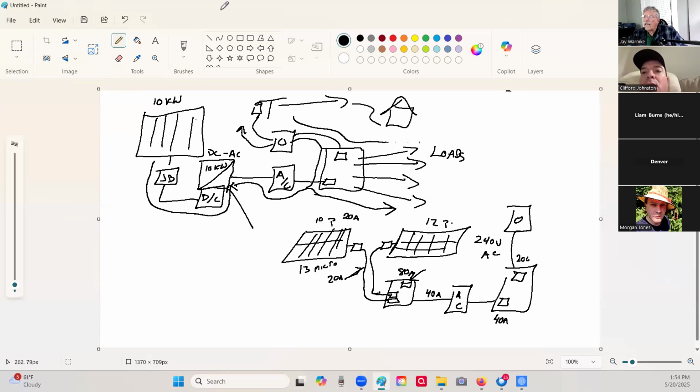Okay. Now, on each one of those microinverters, there's an LED light on the side of it. And if you go and look underneath, if that's green, that means that microinverter is producing. Everything's happy. If it's amber, it means it's producing, but it's not communicating. There's something wrong. Maybe your modem is down or something like that.